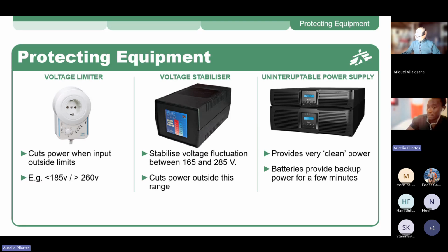So this is where you need a protection for another protective element. It's always a good idea to have an SPD to protect these devices here. Even the AVRs should be protected with an SPD.